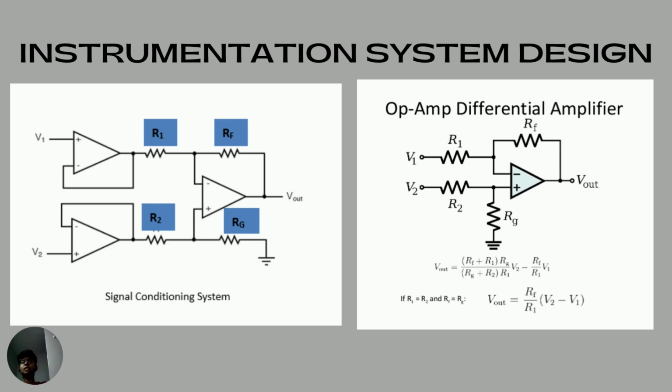Thus, let's say the voltage of V1 is 10, then the voltage at the input of the differential amplifier is 10 as well. It's just with a unity gain. That is what we meant by the voltage follower.